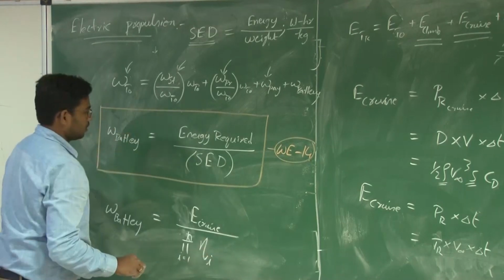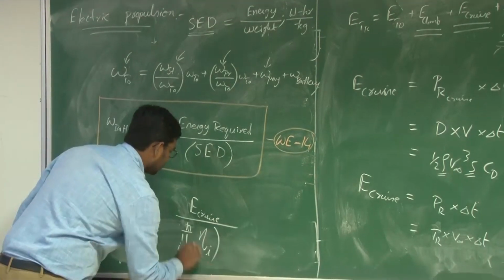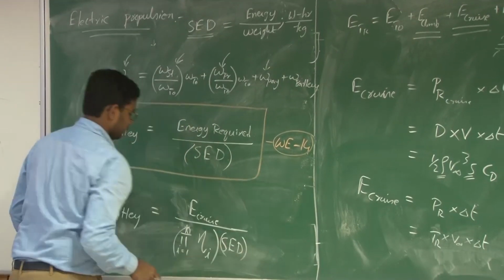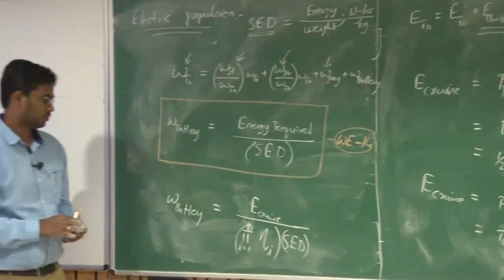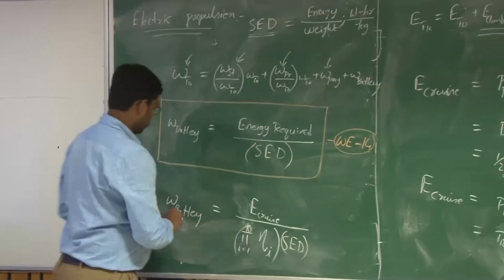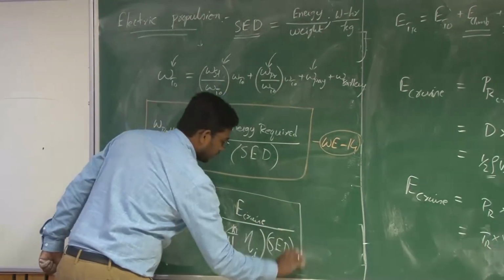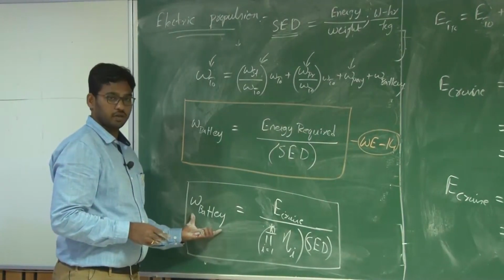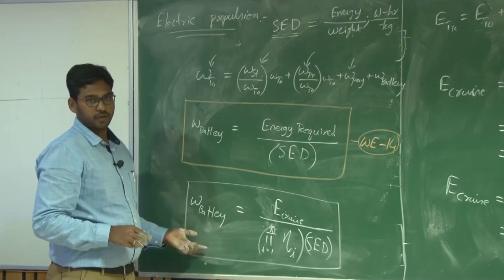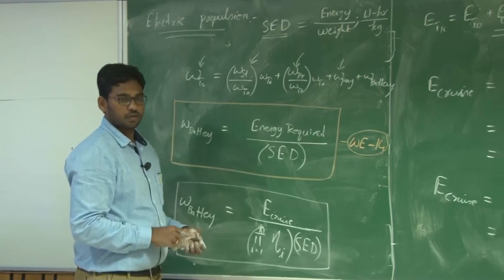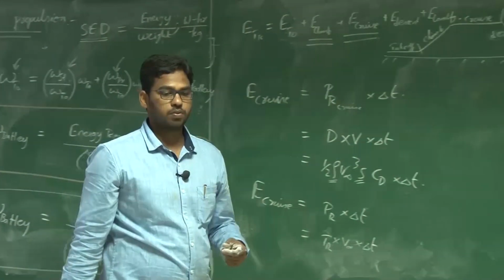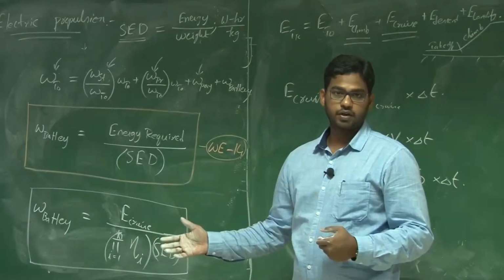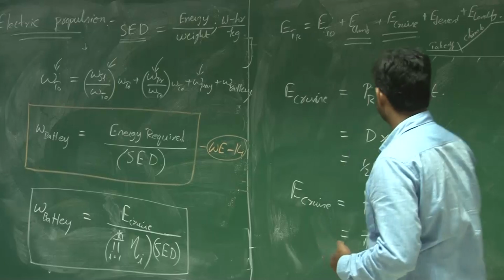This is the weight of the battery, and the ratio of battery weight to total takeoff weight is the battery fraction. Then you will know, say if you want to build a 5 kg UAV, how much battery you need to carry.